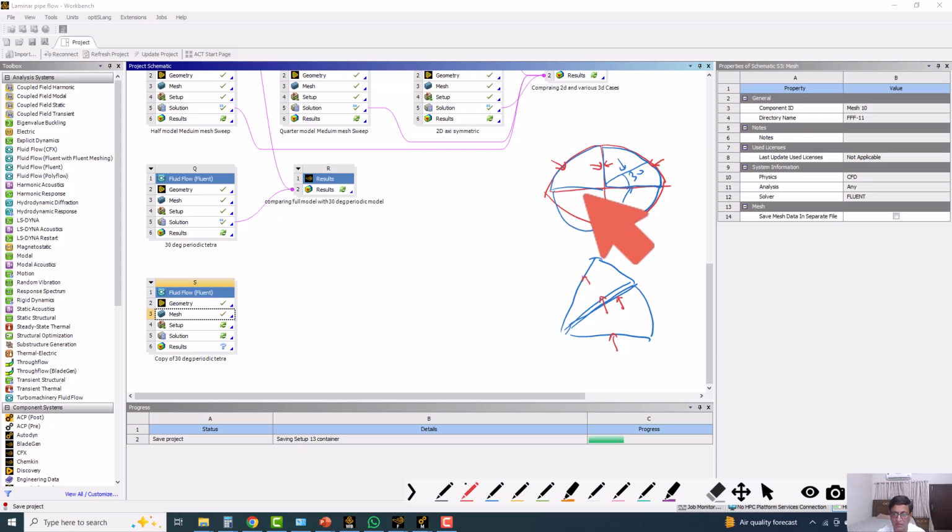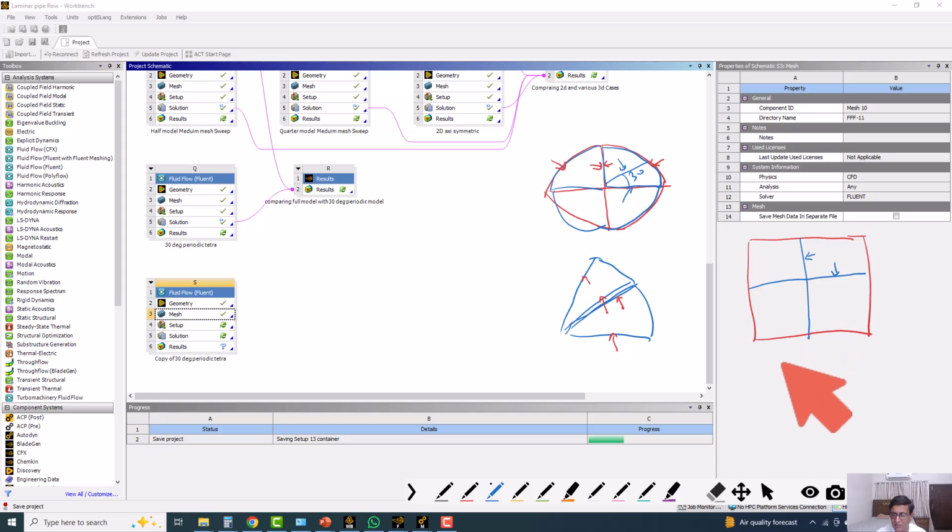It's only possible then. For example, if I have a rectangular geometry, a rectangular pipe or whatever it is, in this case I can only apply the symmetry on these two boundaries. I can make the model one quarter of the whole geometry, but I couldn't make it periodic here, because if I rotate this geometry, I could not get the same geometry. This rotation is only possible when the boundaries are circular. Okay, circular geometry can have periodicity.